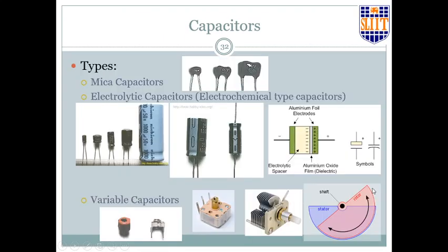We go back. Okay. There this is 2 2 1 J. So what is 2 2 1 J? 220 picofarads plus minus 5%.